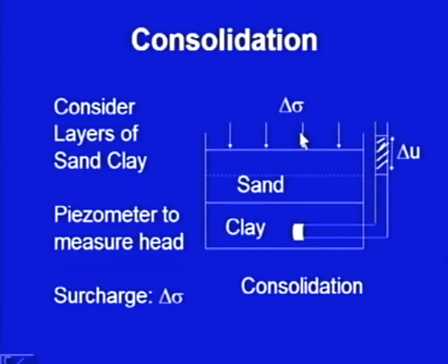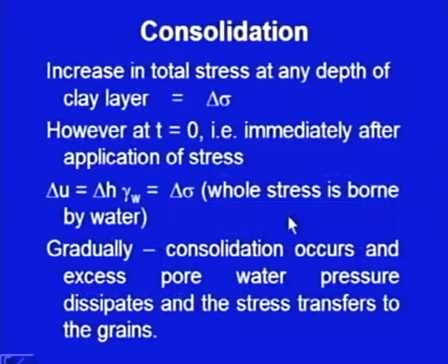Surcharge means some weight, maybe a building is constructed at this place. When you put this surcharge, the weight will be transferred through the sand to this particular clay layer. In the clay layer, though it is completely saturated, initially the water will be bearing that load, and because of that the pressure in the water will be increasing.